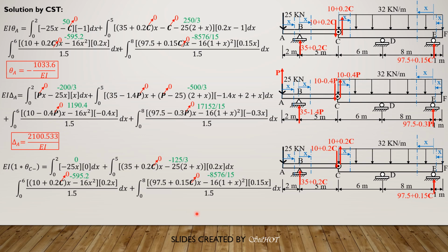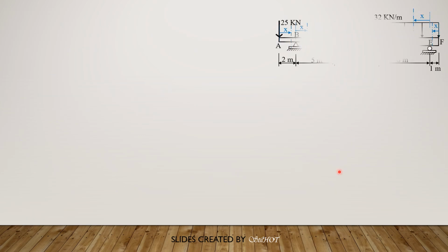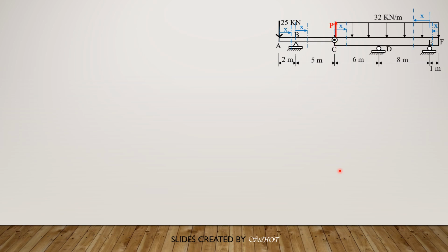Then for the next, we apply a unit upward force at C, just to the right. So take note that it's just to the right. So summation of moment about C is 0. So the reaction in terms of P, reaction times something equals 0. So this reaction at B here is not a function of P.